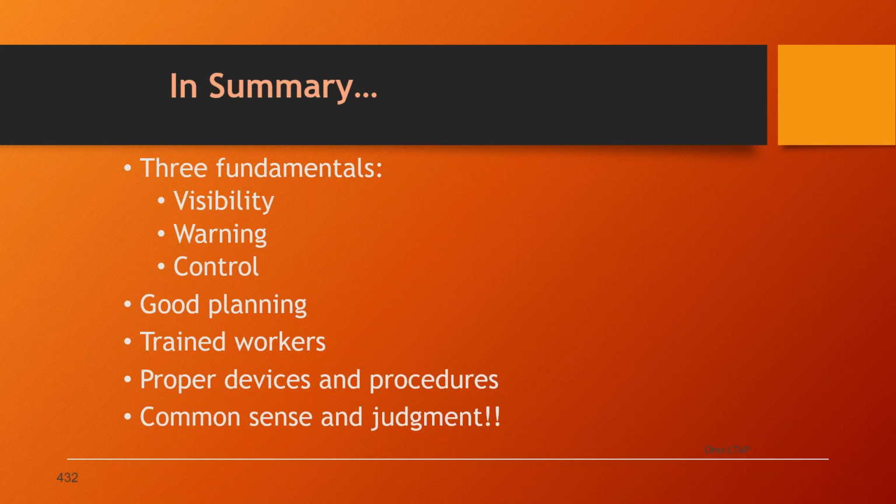Make sure we have, a lane closure usually has at least 3 advanced warning signs. And then, like we talked about in flagging, if we're on a typical 2-lane rural road in Ohio with 55-mile-per-hour traffic, we want you to use 4 advanced warning signs. That be prepared to stop sign can be added to your sign series. But especially when it comes to street closures, can't say enough how important it is to have good planning. So it's definitely more than just one person needed to plan a street closure.